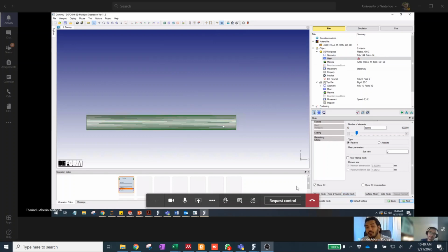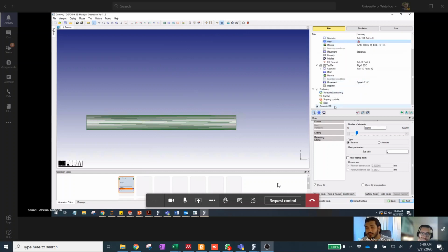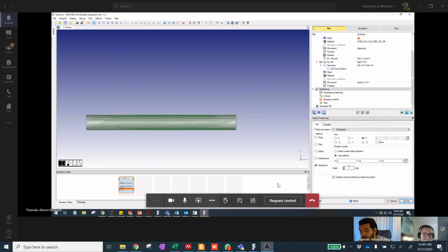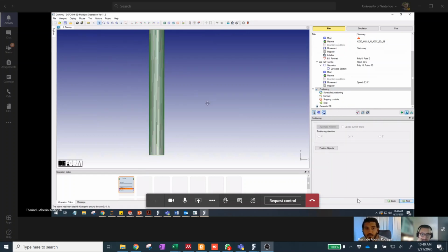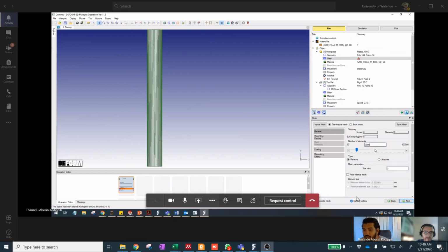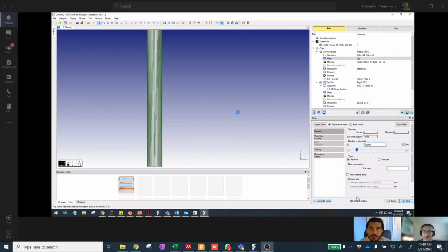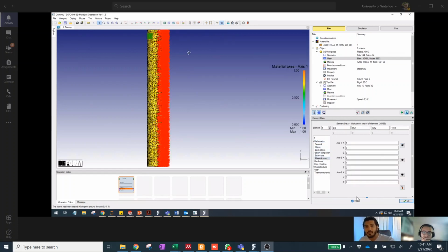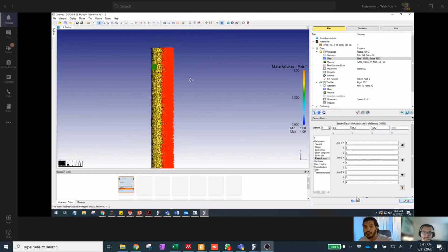For example, now if I wanted to have the material axis changed, what I would do is I would just rotate this object about the z-axis, and now if I mesh it, the material axis 1 should be facing the other direction, the y-axis direction. Or material axis, no, sorry, material axis would still be facing the x. I have to look at that. Yeah, my bad. So material axis 1 still remains the same. It's just now the orientation of the geometry has changed.